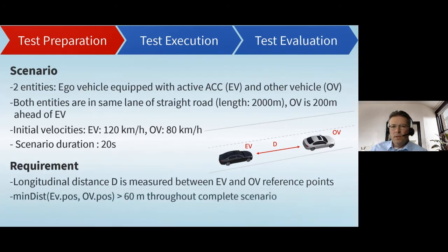Our approach for the proof of concept is to implement the system under test, which is the ACC-equipped vehicle, and also the environment, which is the simulation of the road and the vehicle in front, by means of an industrial solution. We have chosen dSPACE automotive simulation models, short ASM, together with ModelDesk and the VEOS simulator. By this, we are able to focus on the main task, prototyping the generic test case specification.